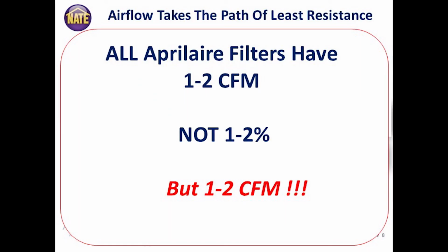Our filters with the self-seal media and the plastic rails that attach to the metal guides give you a very, very tight seal around the perimeter of the filter. The self-seal collapses so you can't get really any dirty air around the back or the front. And of course, the plastic rails that attach the filter to the cabinet, you're not going to get any dirty air sneaking around that. That's just too convoluted of a path.